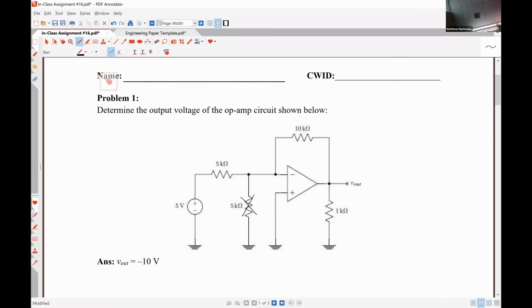So we're left with a feedback resistor here and what I'll call an input resistance here. The configuration that we're looking at has the input resistance placed between our input signal and the inverting input terminal. So that makes this particular amplifier an inverting amplifier.